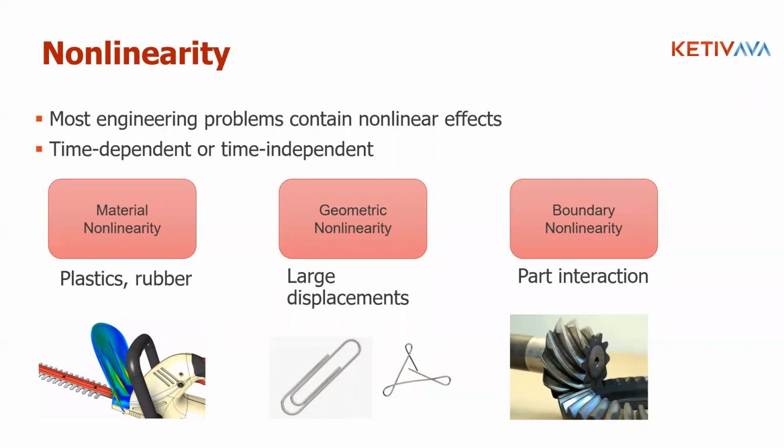Similarly, if you may have heard this before, don't ever try and analyze welds, don't ever try and analyze threads directly in FEA. The reason for that is kind of the same. When you're talking about threads, again, the nature of contact is not symmetric. The nature of contact is very, very complex between the threads.